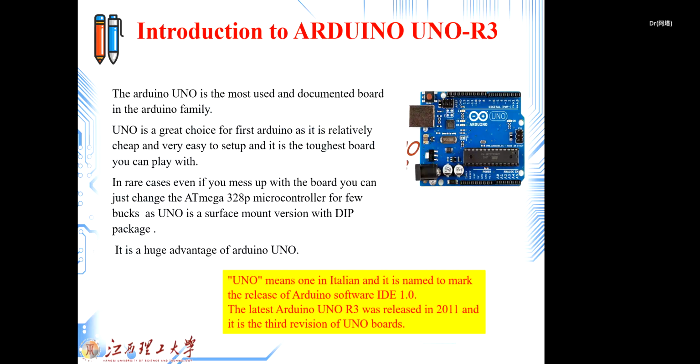One of the nice things in the Arduino Uno is that this type of board can be used as the programmer for other Arduino boards. I mean, suppose today you decide to make your own Arduino board, simply you can do it. Then how should you use the bootloader for the Arduino? With the help of the Uno board, you can program the IC and then put it on the chipset. This is the most significant thing about Arduino Uno that I can tell you.